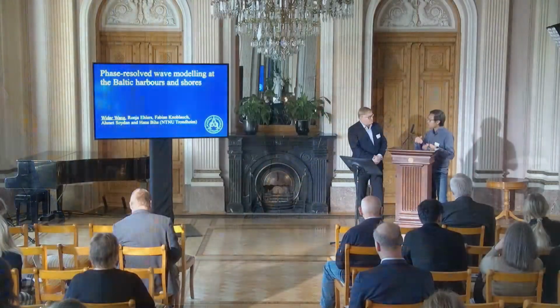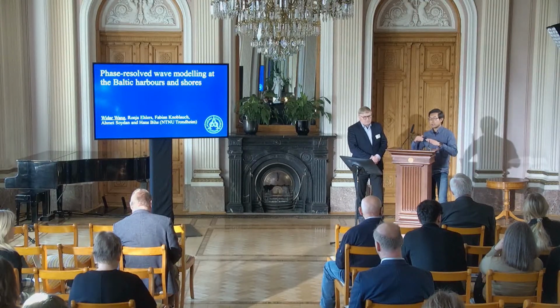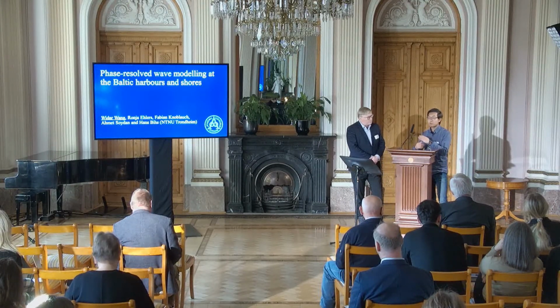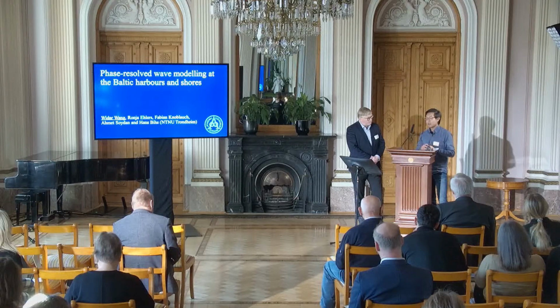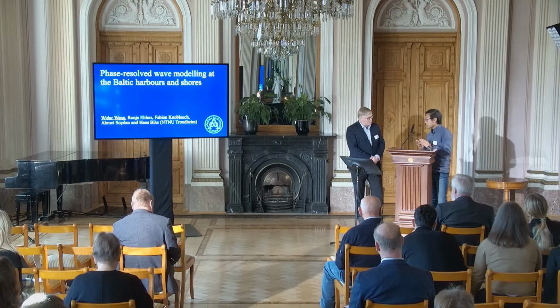Yeah, thank you very much. That's a very good question. I think there are two, probably three main differences between Norwegian harbors and Baltic harbors. In the Norwegian area, indeed, because of the existence of fjords and a lot of harbors along the fjords, the water depth changes are more drastic. You can have almost a 45-degree subsea slope outside the harbor. You move out 500 meters, then you already have 500 meters water depth. So that's a very drastic change. But also many Norwegian harbors are more prone to large swells from the North Sea. So you have very long waves that can penetrate deep into the harbor. But the Norwegian coast is very rocky, mostly.